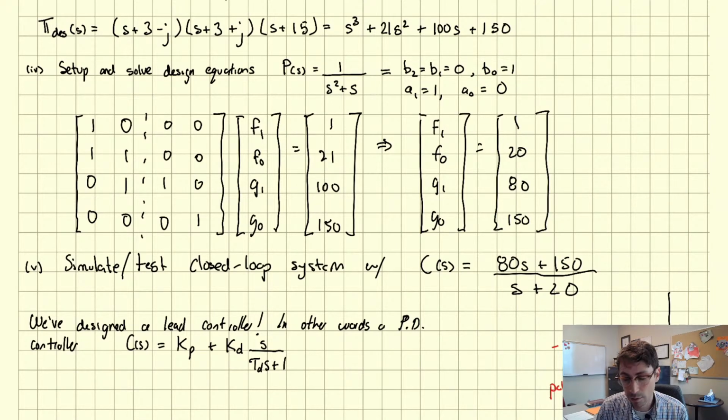The denominator, the coefficient on s to the power of 1 is 1, and the coefficient on s to the power of 0 is 0. Okay, so I've now got my a's and b's. And now I fill them in. So the coefficients of the denominator are 1, a1, and a0. So 1, a1, a0, pad with zeros.